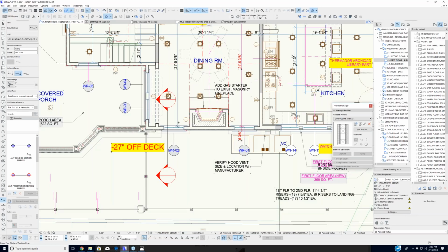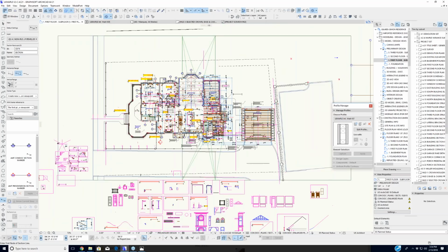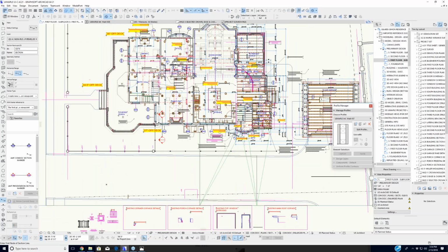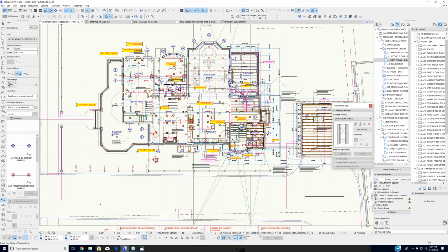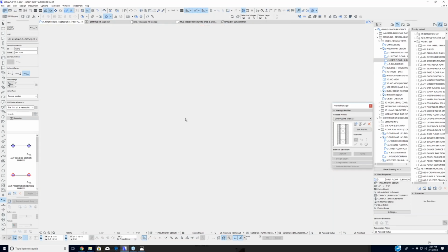But what you also want are sections at a minimum 4, 2 of them going left to right and 2 of them going top to bottom. That is so you can very quickly just drag one of these in place and open it, and not have to spend the time to come over here, create one, put it there, delete it, rotate this. That's burning time. So I'll have these at least 4 always show up on the model. So I'm going to open up this section just so you get an idea of what an actual cut looks like.